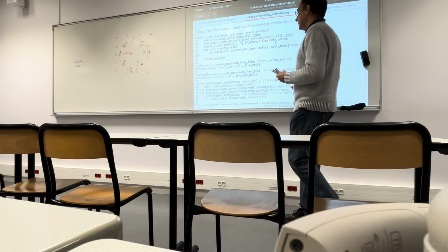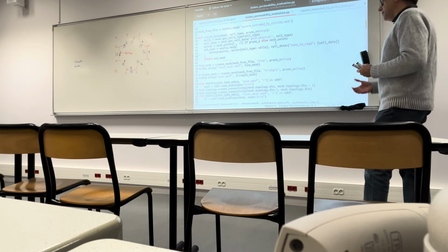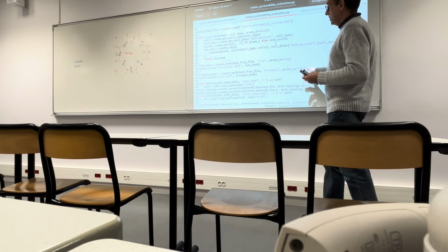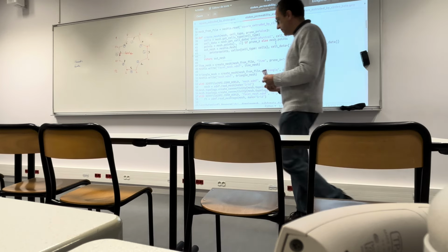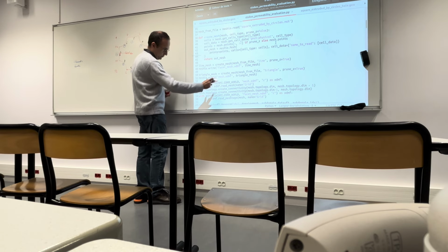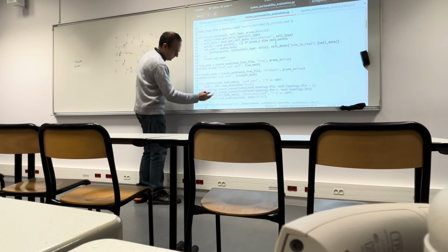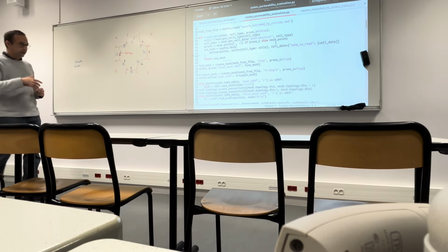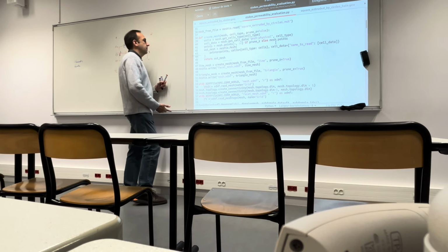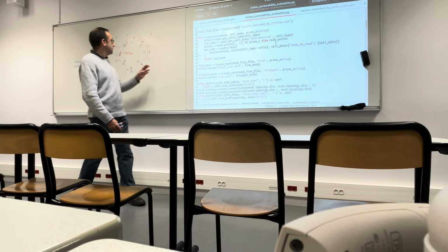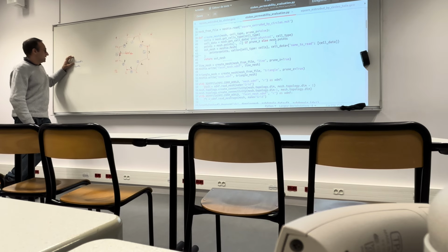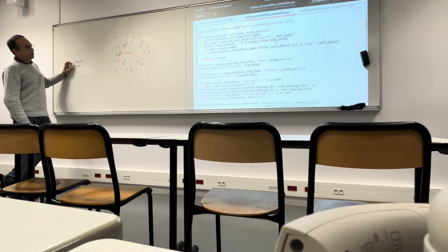And so this is the last step, because we are finally reading these files and defining these two quantities, mesh equal to something and ft equal to something. So we are defining what is later exploited in the code as the mesh and as the facets associated to the mesh. So the list of elements and the list of facets of our discretization.